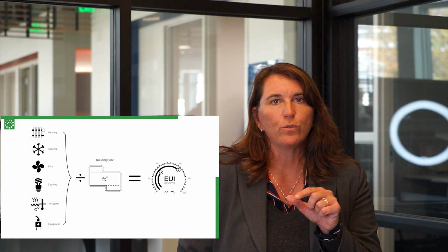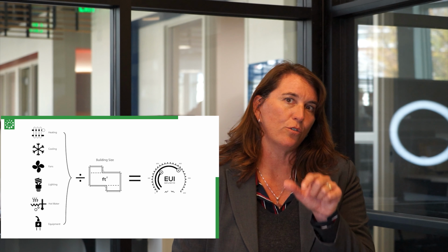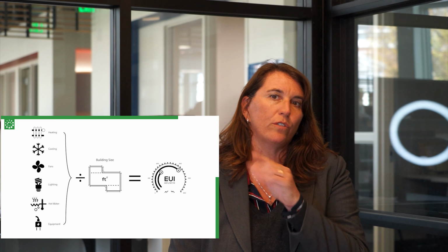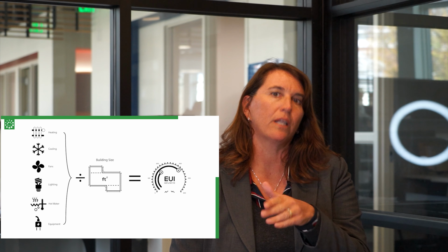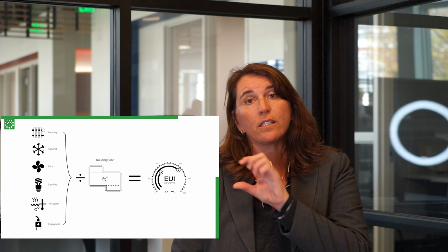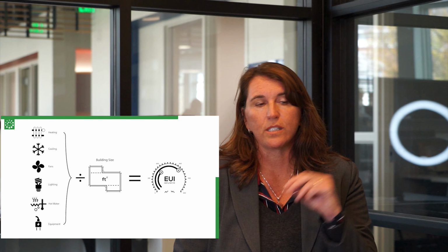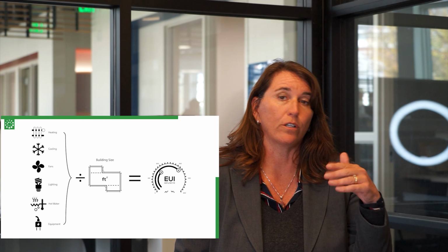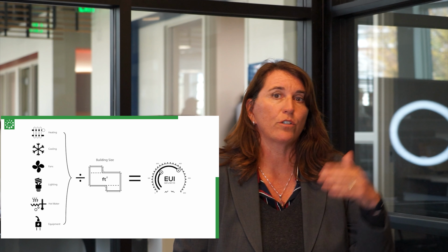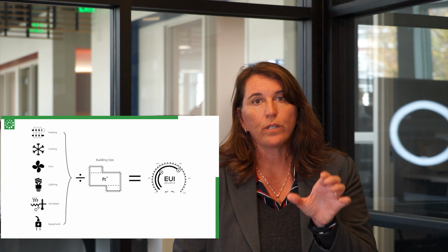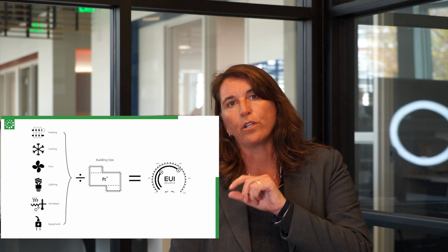And a kBTU is basically the energy that is consumed by the building. You divide it by the square footage of the building, and that's total for an entire year. So it's the kBTU, whether that's converted from electricity or converted from gas, it all can go into a kBTU per square foot per year. And that is the metric that Energy Star uses as we start to look at schools and their energy use, and we start to compare them with each other.